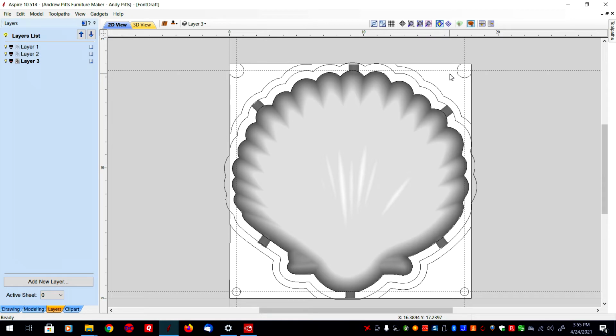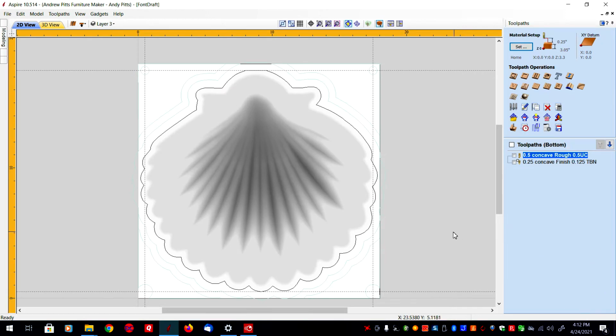So you've got to really think hard when you're doing deep work like this about what the machine is going to do, and I didn't quite figure it all out before I started cutting, but I figured it out before I started breaking things, which means I could just stop the cutting, go back and make a new toolpath file to get rid of these parts here, leaving a nice place where I wouldn't cut into my hold down screws. Okay, so I'm ready to start cutting.